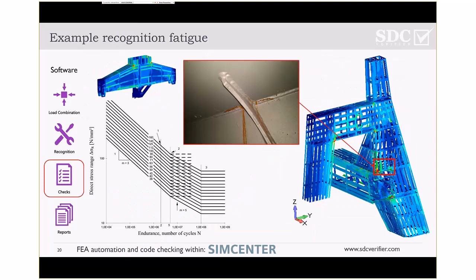To give you an example, this is a crane we did. This is a 40-year-old crane, so we can even track the calculation and the usage factor over these 40 years. We calculated that, and after that we could do inspection, because you cannot inspect 10 kilometers or 100 kilometers of welds. You first need to see where to look.